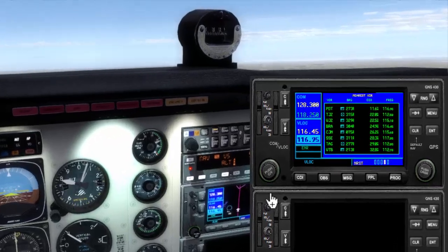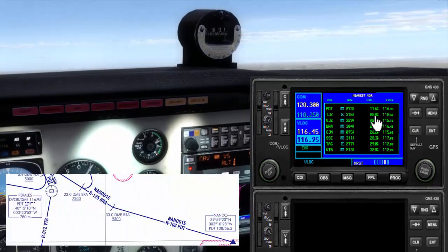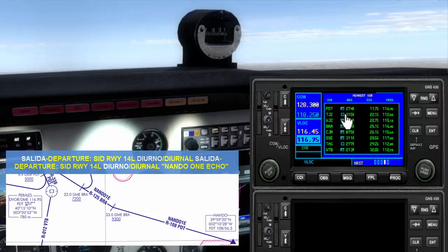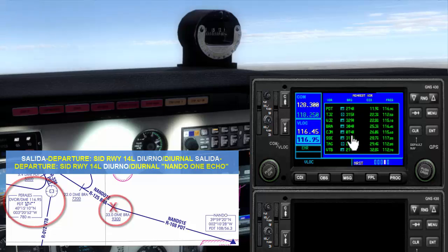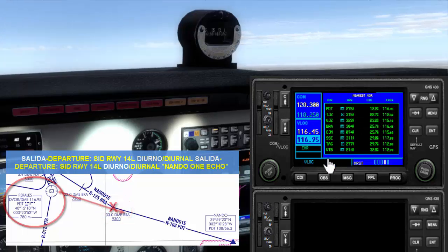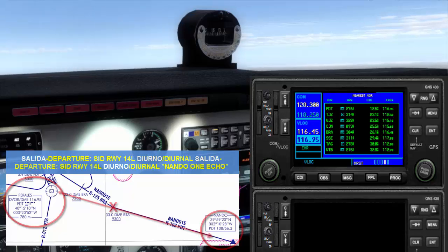Okay, well, the next thing we will do is to organize the flight, and we will follow, when we reach that point, 53 nautical miles from the Barajas VOR, our altitude at that point must be 9,300 feet. When we reach that point, automatically we will switch to a different radial from a different VOR, and that is, we will follow the radial 108 from the Papa Delta Tango, PDT.